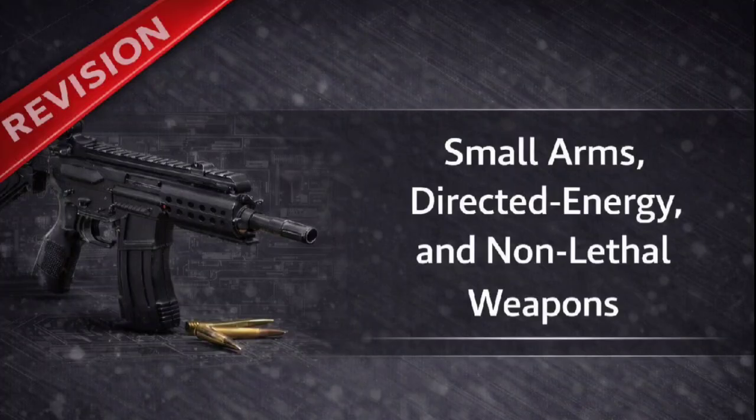Once the firing mechanism is released, the bullet starts its flight, but the weapon itself moves. We know recoil is the rearward force, but this action also creates muzzle movement. What are the three mechanical factors that combine to create this destabilizing movement? Recoil is the primary rearward reaction force applied through the base of the cartridge case. This force causes the muzzle to move because the force is almost never applied perfectly in line with the rifle's bore. There are offsets. There are three key offsets.